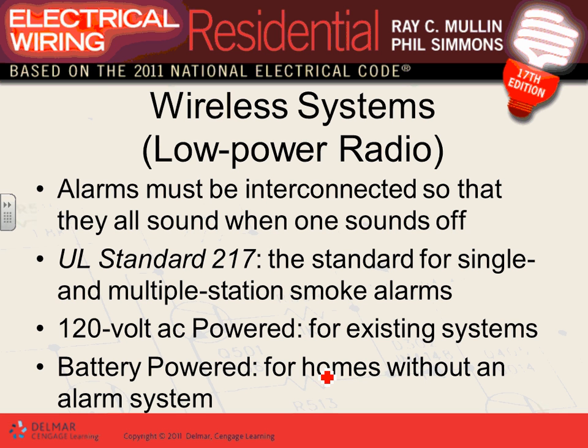Wireless systems. Guys, I don't believe it's approved by 72, but for remodeling buildings, you can use devices powered with batteries, and they can talk wirelessly to each other. If one of them goes off, all of them go off. Has anybody installed a system like this? You can put a smoke detector in the basement and on every level, wherever it's required, and they talk wirelessly to each other.